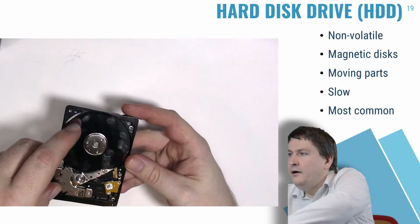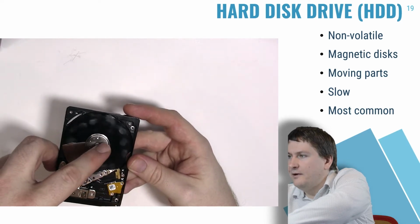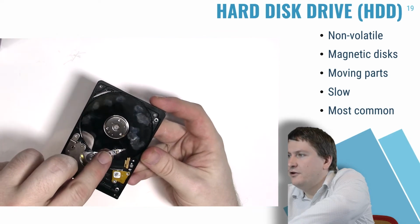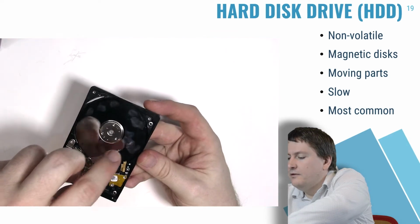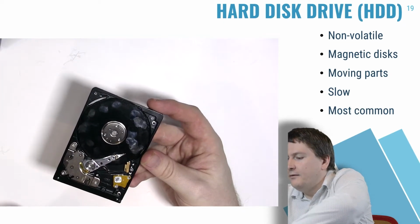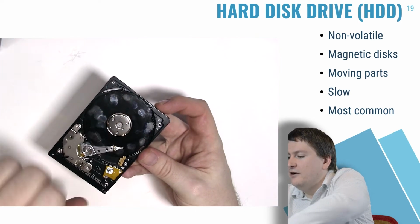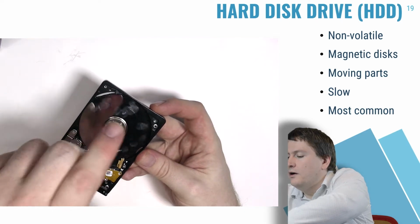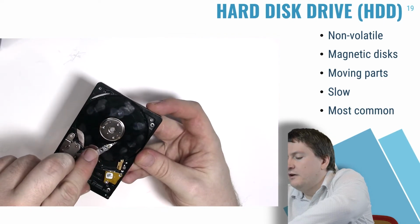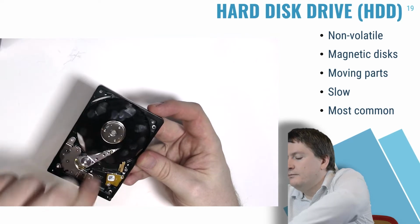And this is a magnetic platter where all the data is stored. The way this works is this spins really fast, faster than I could spin with my finger, and this read head goes back and forth to find the sectors on it that you're looking for. And it can also write to it. On the tip there is a little magnet that it can control to either read data or write data. Now it's hard to see in this, but there's actually a stack of multiple platters. So it's not just this one platter, there's also one underneath it, and sometimes on bigger ones, there's even one underneath that. And there's another head that goes underneath the disk. Back and forth like that.